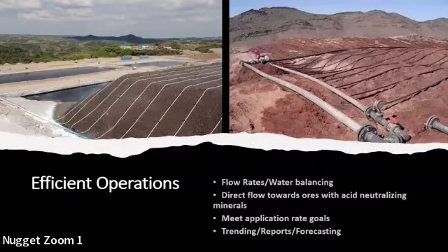Why this backward approach? With many heap leachers that I've been involved with, we suggest that you do a detailed permeability test under varying load before you decide that. Any comment on that? Unfortunately, we weren't involved out there prior to this, so I'm not sure of the story behind that, but you're absolutely right. Implementing a study like this at the beginning, in the feasibility stage, would hopefully save you a headache in the long run.